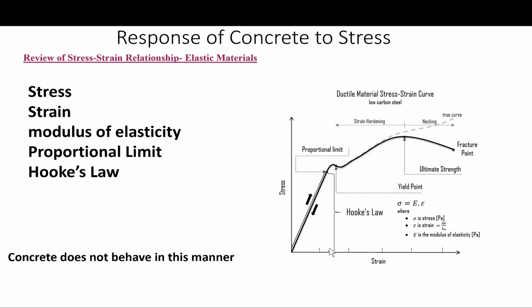Okay, if we look at the curve and we see these different items or terms I just explained, the Young's modulus of elasticity is basically the elastic modulus for tensile and compressive stress in the linear elasticity regime, as you can see here, of a uniaxial deformation, and it's usually assessed by tensile tests, typically for ductile materials mostly.